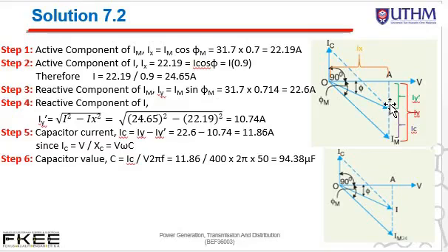Later, we calculate the reactive component of the motor current, which is over here, IY, and from there we have to calculate the reactive component of I. We can use the Pythagoras theorem in order to calculate the reactive component of I.